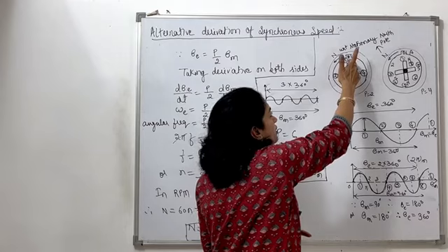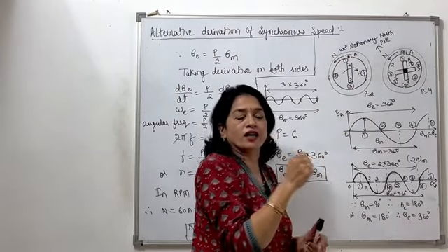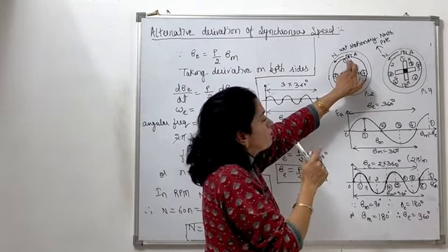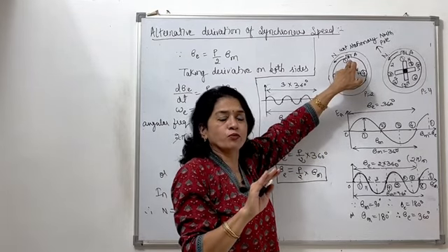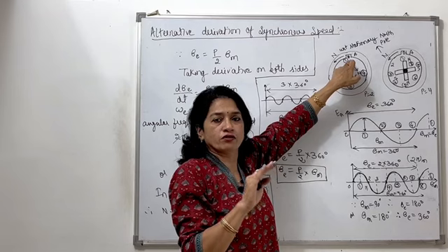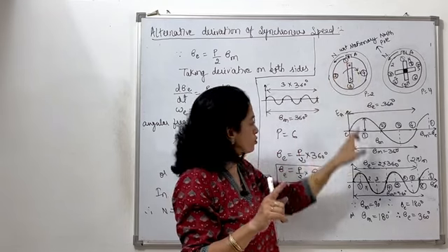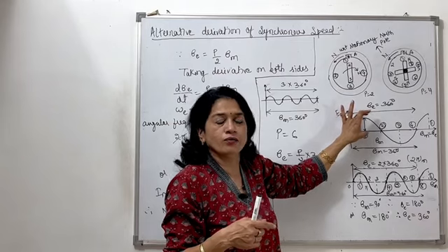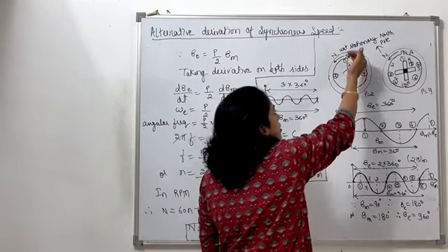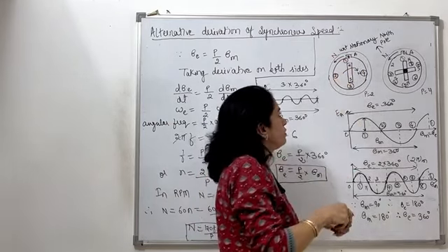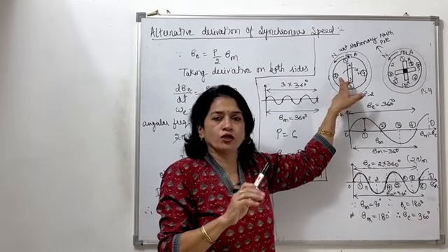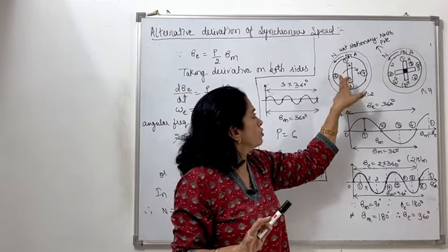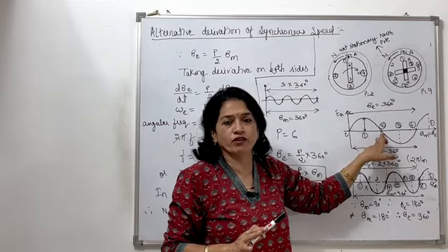That means when the conductor is against the north pole, it has the maximum EMF induced in it, and I identify that relative position of the conductor with respect to the north pole as 1. I am showing that position over here. So the EMF has positive polarity and the maximum EMF is there. Now the conductor comes to the second position. Here it is a neutral position, so neither positive nor negative EMF is induced, zero EMF is there. This second position is identified over the waveform here.